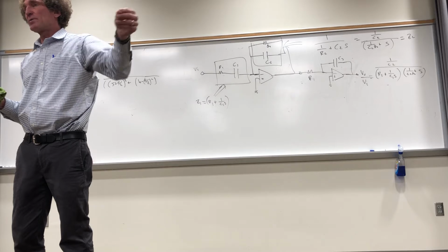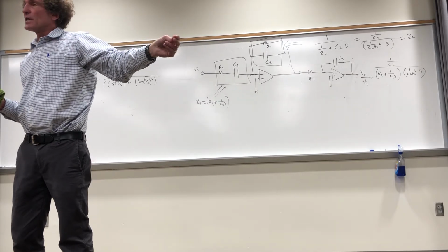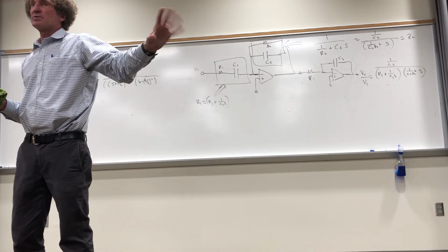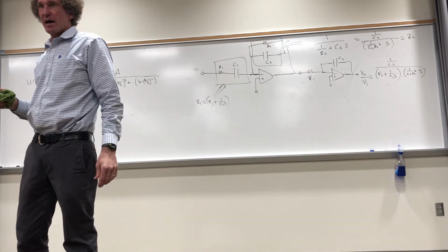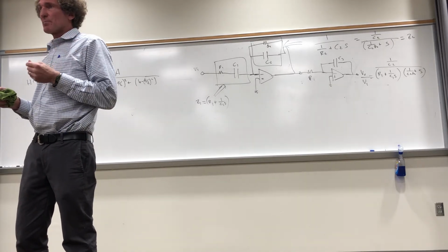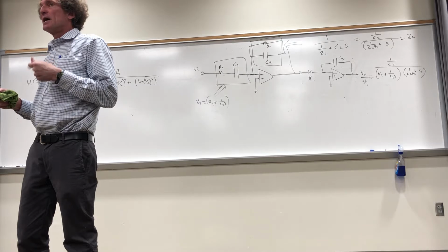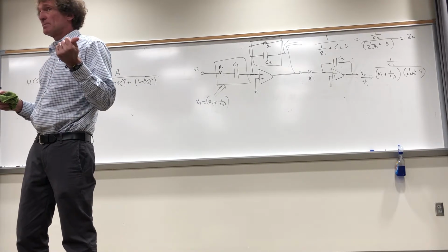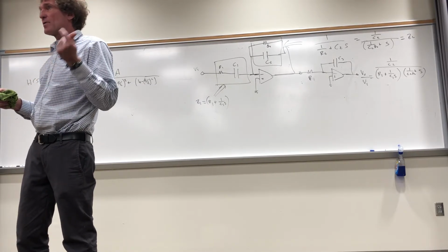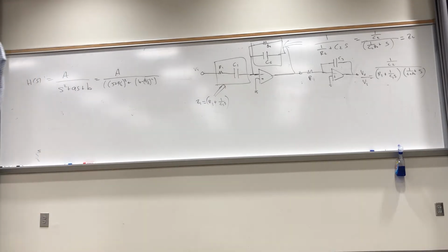They're getting a little more complicated as we go, but you can realize now any of the H of S functions that we have with electronics, with operational amplifiers, capacitors, and resistors, including summers, 1 over S, 1 over S plus A, 1 over S plus A squared or cubed, and 1 over S squared plus AS plus B. Follow me, class? All right, and that's real important.